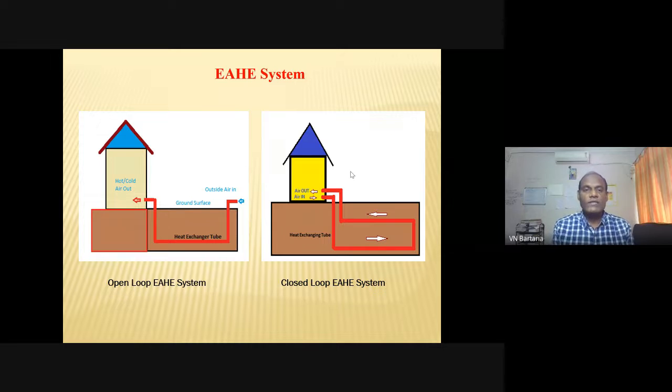and the advantage from the soil or underground soil can be obtained through the pipes. So air is supplied to the underground laid tubes, where it comes with the lowering of temperature or increasing of temperature, and air can be cooled or heated from the soil, and heating and cooling effect is obtained naturally.